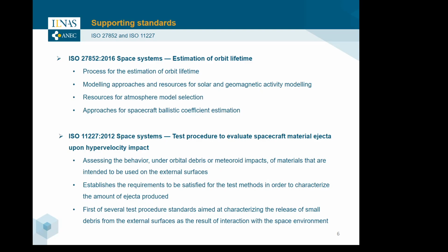ISO 11227, test procedure to evaluate spacecraft material ejecta upon hypervelocity impact, is applicable to spacecraft and launch vehicles operating in all types of Earth orbits. The experimental procedure defines the type of facility to be used, the size, velocity, and type of projectile, the evaluation of impact ejecta released, the reporting of test results, and the quality requirements to be used. It provides data that need to be taken into account in the selection of outer spacecraft materials, though the selection is not based on these criteria alone.